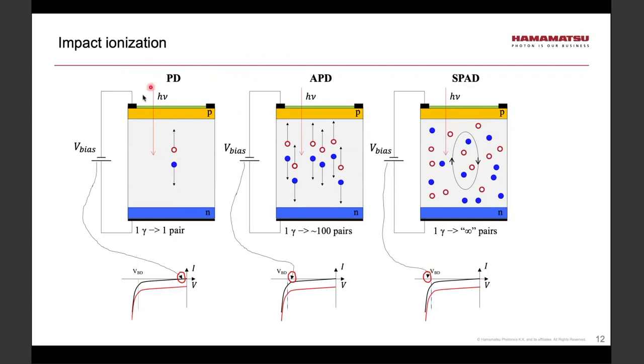Please note that these depictions of the depletion region or the PN structure are not to scale. So it's highly exaggerated size of the depletion region. In the depletion region, there is electric field which separates these two charge carriers. Therefore, the electron drifts towards the N region and the hole drifts towards the P region. And you can think of electron then recombining with the hole, producing a photocurrent.